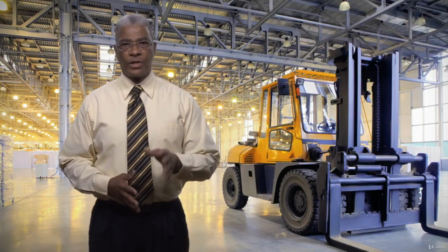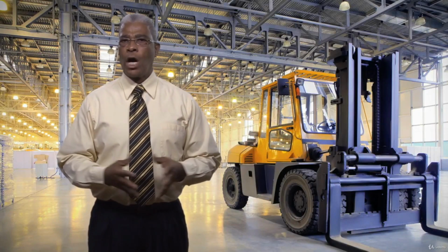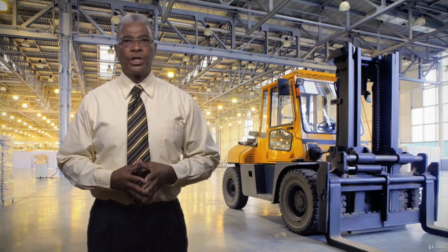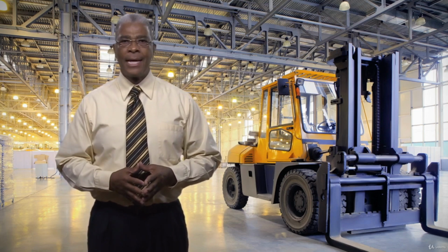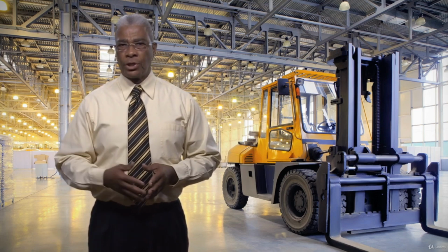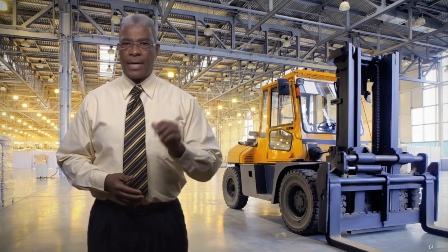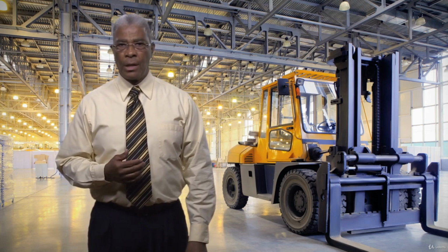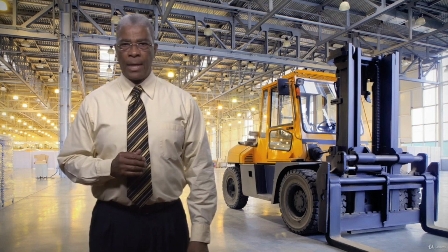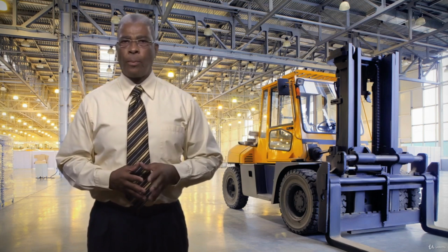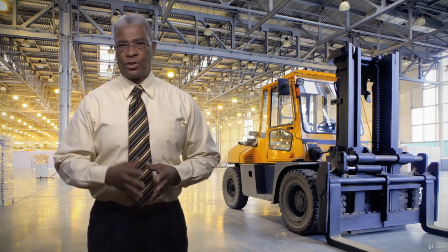Lockout-tagout requirements cover servicing and maintenance of machines and equipment for unexpected energization or startup of machines or equipment, or the release of stored energy that would cause injury to employees. It does not cover construction, agriculture, and maritime equipment, electric utilities, electrical exposure covered by Subpart S, oil and gas well drilling and servicing, work on cord and plug connected equipment that is unplugged and under control of the employee, and gas, steam, water, or petroleum hot tap operations under certain circumstances.